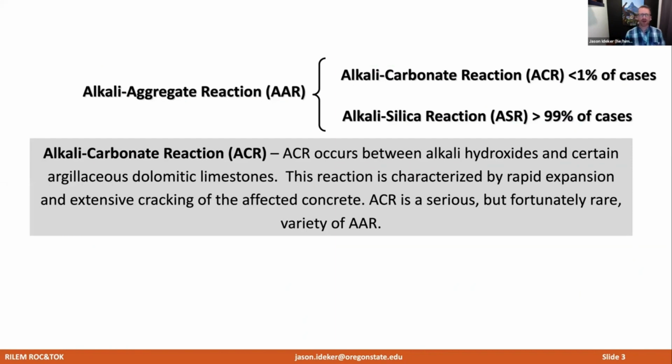We're not going to talk too much about ACR today, but just so that you know, it's a reaction that occurs between alkali hydroxides and certain argillaceous dolomitic limestones. And that reaction is characterized by a very rapid expansion and extensive cracking of the affected concrete. ACR is quite serious because of how rapid and damaging the expansion is, but fortunately it's quite a rare variety of AAR, and we generally know which aggregate sources those are linked to.